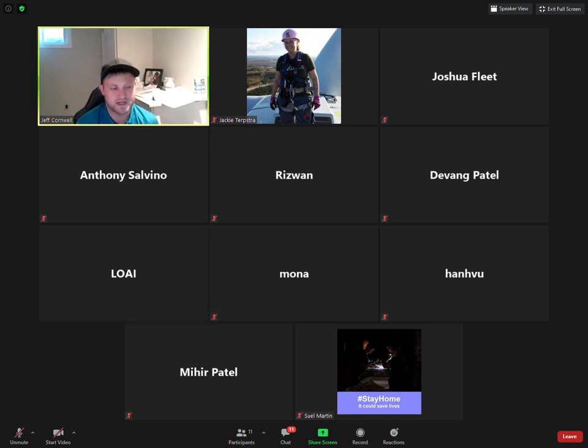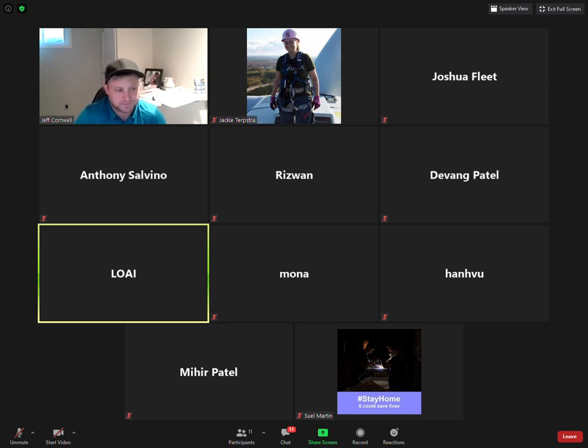If what we did in last class, last week, made sense to you, then all you're really doing is those extra few steps, which are creating a signal control. You're clicking that signal control button and you are making a coordination group. Then you're selecting your coordination group, making sure you have identical cycle lengths, and then you are basically just drawing that route and adjusting your offsets. So once you get the basic information created, it really should not take you much time to go through and do the coordination part of it. Okay. Hopefully it will go smooth. Thank you. Yeah, no problem.